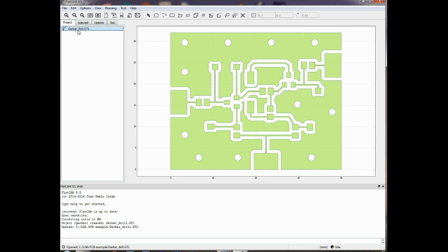For this top layer, from the Gerber file we generate a geometry, which is effectively the paths that are going to be milled. Then from that geometry, the next stage is to generate tooling paths, and from the tooling paths, the last stage is to generate the G-code, which is going to be used by my CNC controller to actually perform the milling, which is just effectively X, Y, Z, go here, go there, go up, go down.